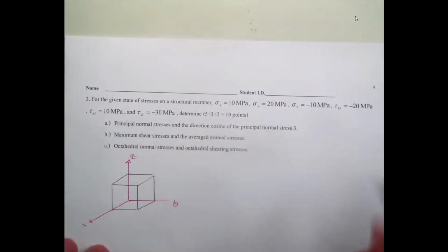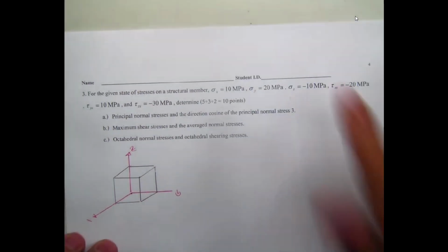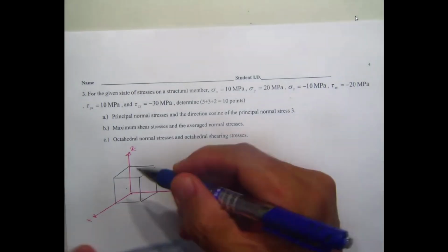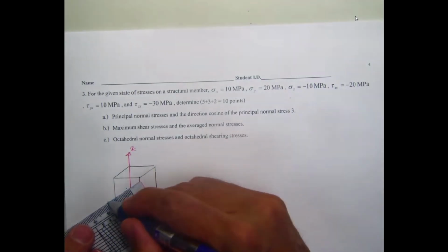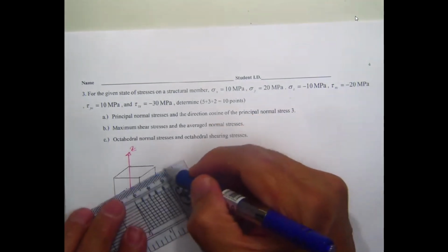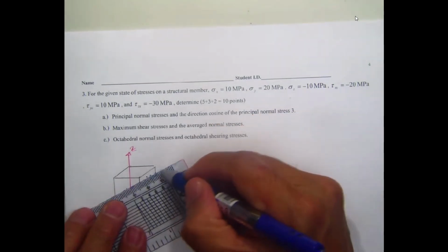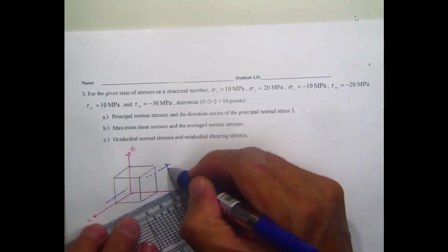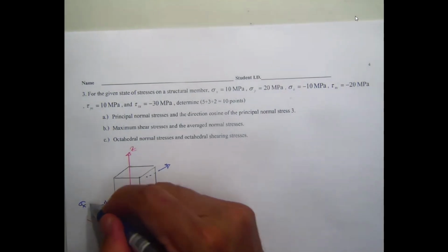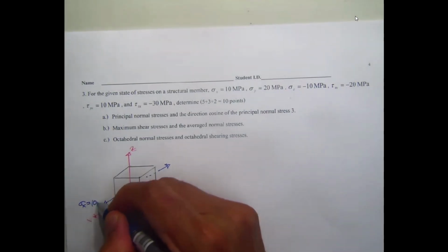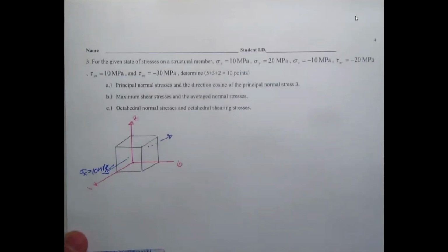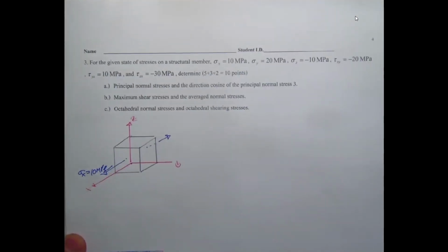What is going to be the stress represented over here? Sigma sub x is the stress acting on the surface perpendicular to the x direction, and this is sigma x equal to 10 megapascal. How about sigma y?